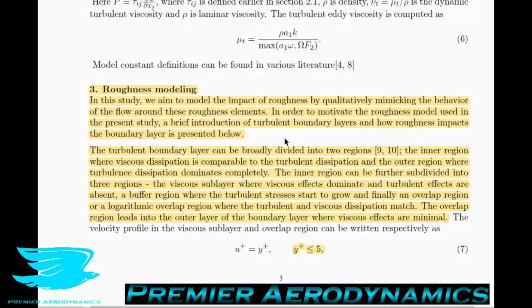And there are some turbulence models, for example, the K epsilon model, where you can go 30 or more, and they say that it's okay, but the K epsilon model is rubbish anyway, so it's not really much of an issue either way. But for regular turbulence models that are actually good, you want to have a Y plus value of 1 or at most 5 or less.